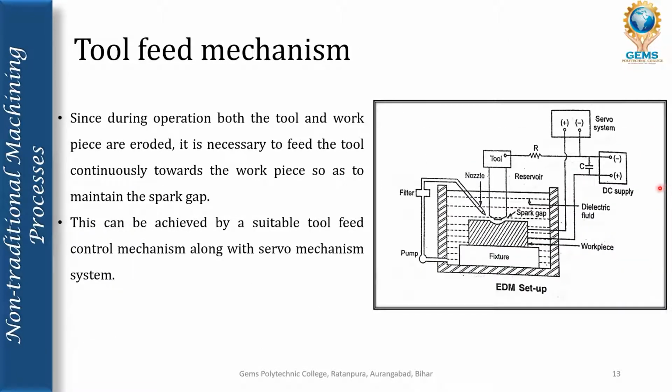Now it comes to the tool feed mechanism. Since during operation both the tool and workpiece are eroded, mostly the workpiece gets eroded, and as it goes on the tool also gets eroded. So it is necessary to feed the tool. Feeding the tool means the tool has to move continuously towards the workpiece so as to maintain the spark gap.